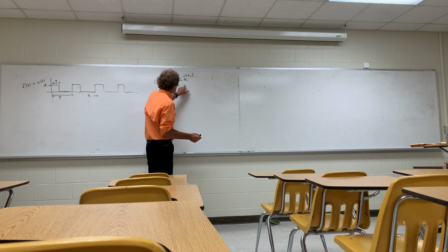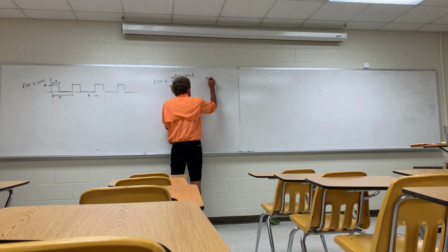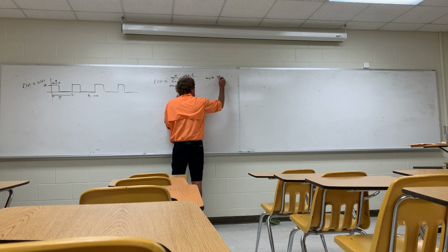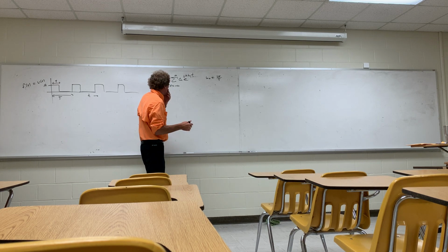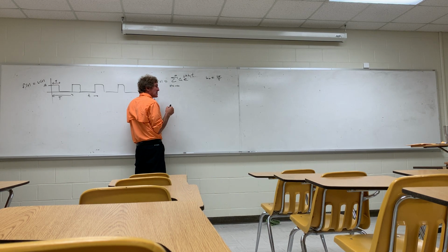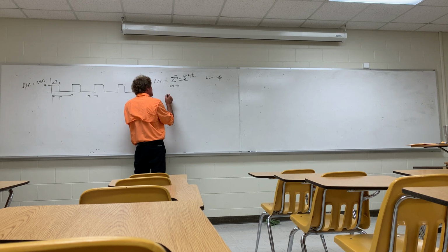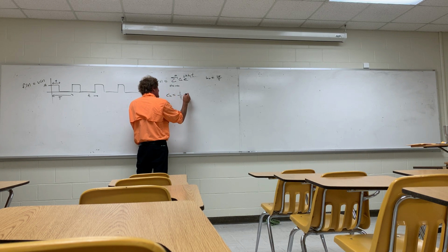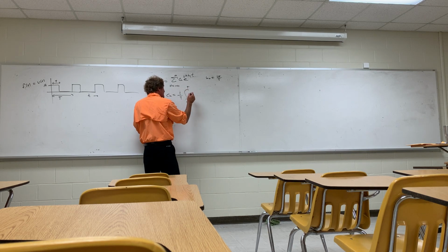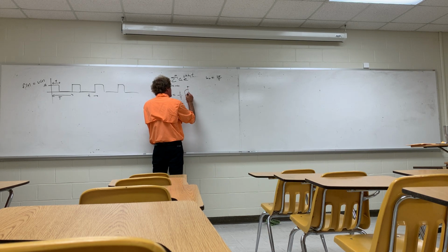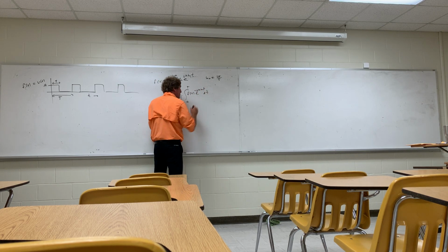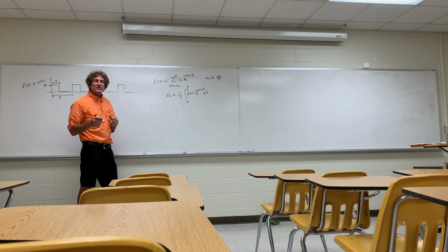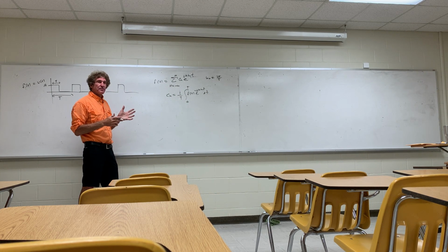So if I have that, I know that first of all, omega naught is simply 2 pi over the period, the repetitive period T, if you remember that, right? That's the fundamental frequency it's called. And to get c of n, usually you had to say c of n is equal to 1 over the period, the integral over the period of f of t times e to the minus j n omega naught t dt. Y'all remember doing that? That was a standard way you calculated the coefficient c. With me so far? All right.